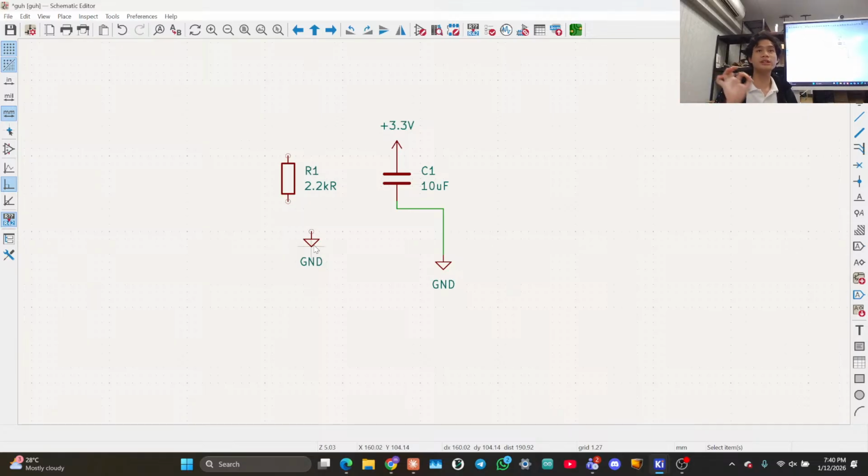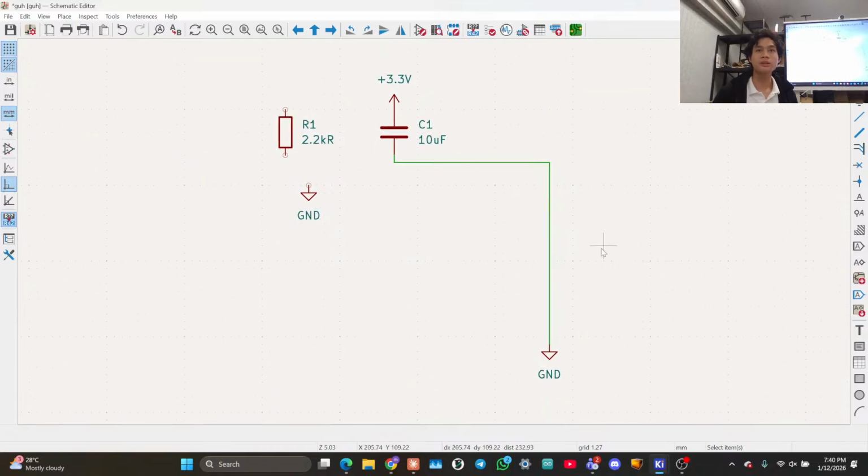Okay, now to reiterate, this is a schematic. All of these are ideal wires. Okay? So you should not go, oh, look at this long ground, I should add an inductor here now to model the impedance. No, do not do that. Because if you do that, then you are going to go into your PCB and you're going to have an inductor which you also have to place, and no, you've just added more inductance to the thing, right? So we assume these to be ideal wires, and in the PCB layout later, we will just make them as ideal as possible. Okay, you don't need to model the parasitic RLC components right now.